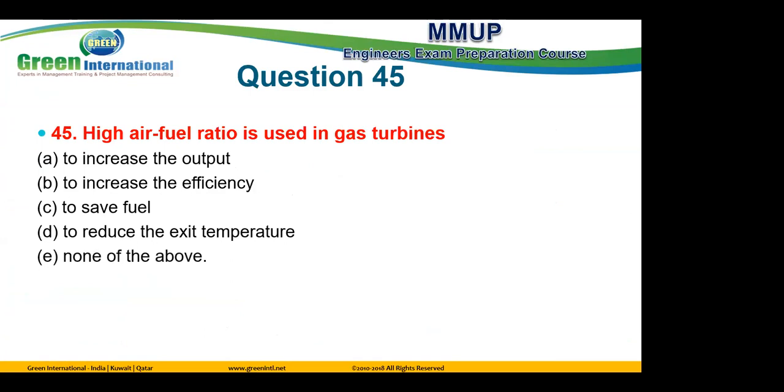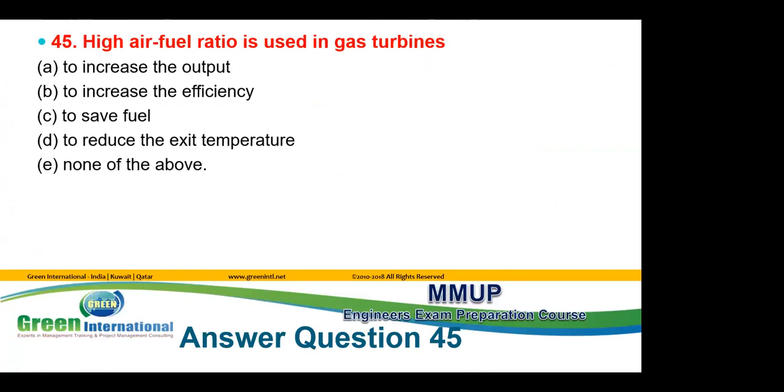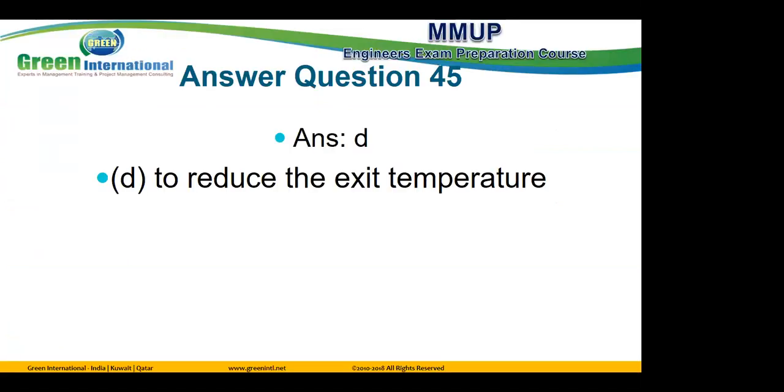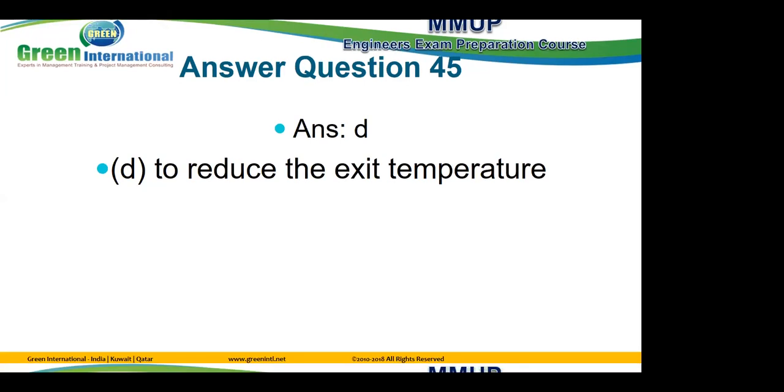To increase the efficiency, or to reduce the exit temperature, because we have more excess air. This air is not burning and is used only to decrease the exit temperature.